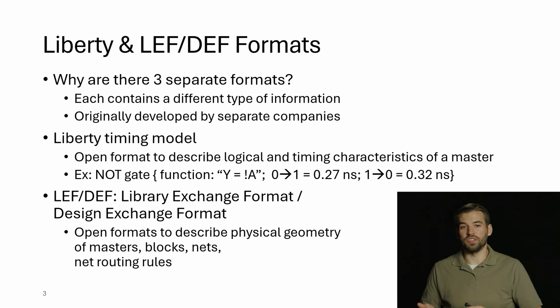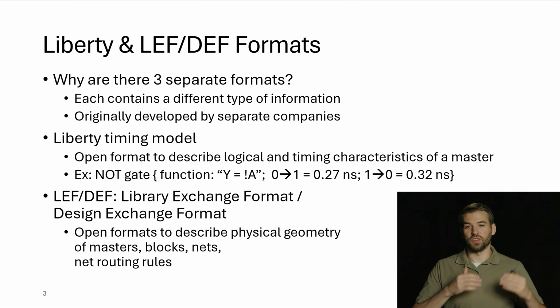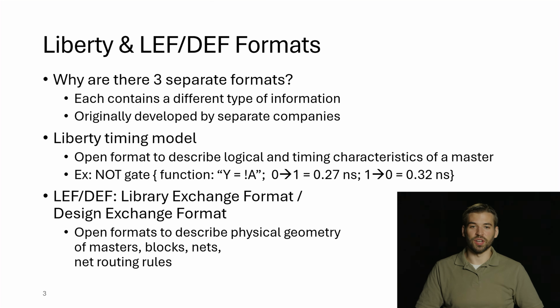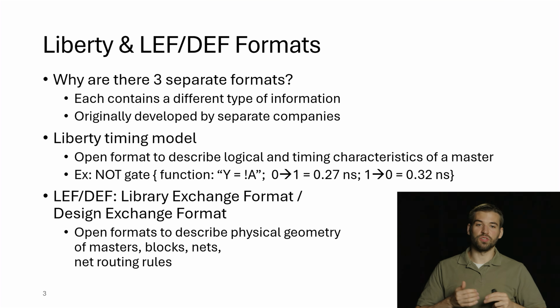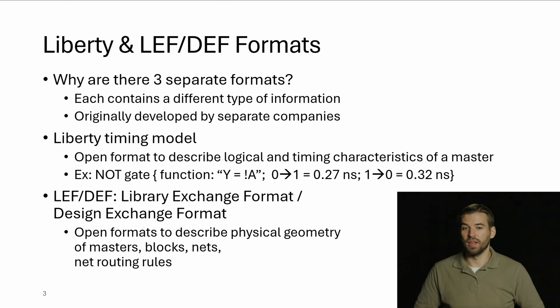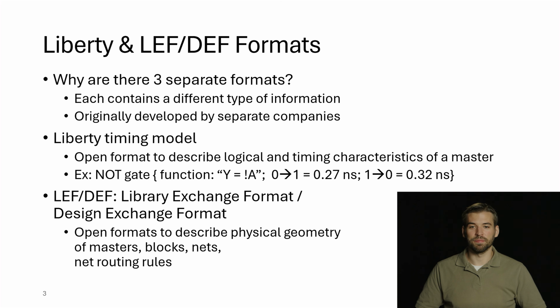Here, LEF and DEF stand for Library Exchange Format and Design Exchange Format, respectively. Whereas Liberty is concerned much more with the logical information, these formats are concerned with the physical geometries of the objects, including masters, nets, and blocks. These formats store the actual shapes and sizes of objects if they were laid out in a physical chip. Nothing in the Liberty format, with maybe a couple of exceptions, is actually concerned with the physical shapes of the master or the circuit. That's where LEF and DEF come in.